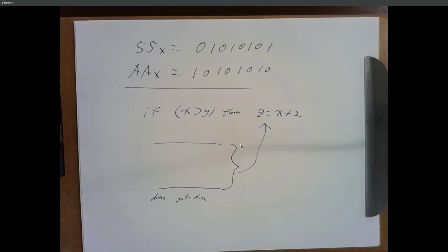You'll see questions related to input and output. Okay, so TRIS say port B, ADCON1, that sort of stuff. You'll see questions related to interrupts. So writing some interrupt code to do things in response to certain interrupts. So having to set up the interrupt system, the INTCON registers, the PIR register, putting code at location 8 or 18, putting code in the beginning that branches to some main section, all that stuff that we've done every time we've dealt with interrupts.